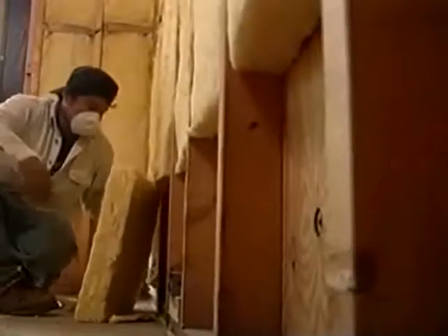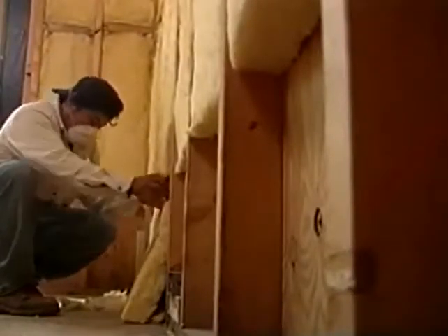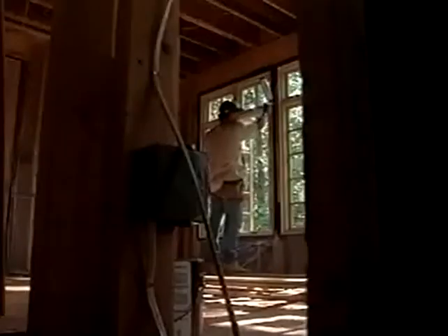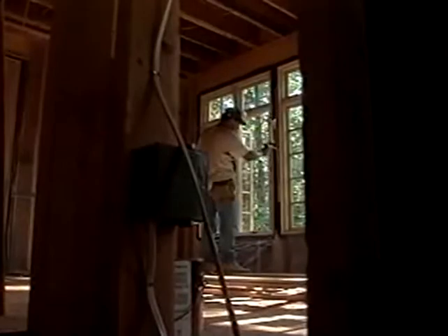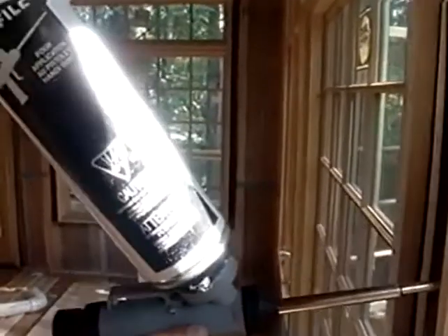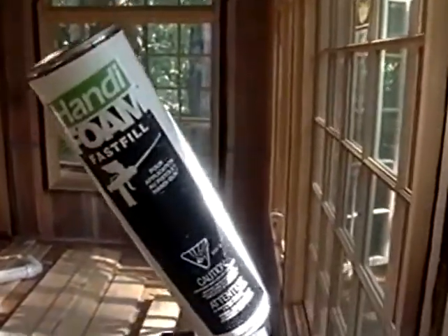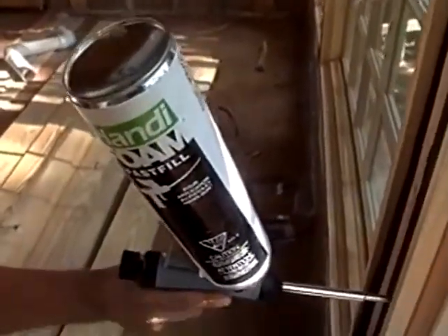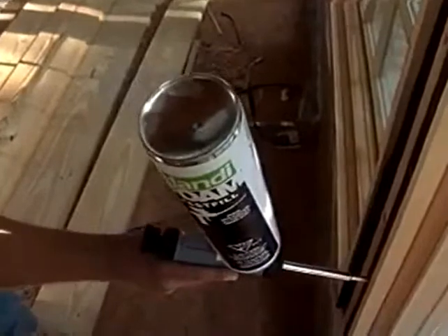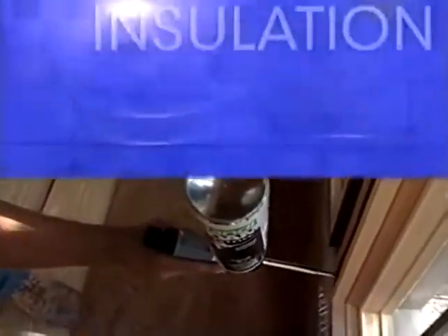One more word about it. There's absolutely nothing wrong with this house. Proper insulation of a home is important to its overall comfort. But without proper air sealing, some of that work just goes out the window. The air sealing of a home involves closing up any cracks or holes that allow unwanted air to leak in or out. Imagine leaving a window in your house open all day, year-round.